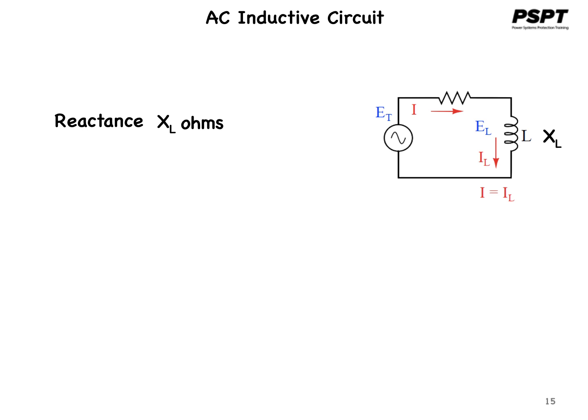Since inductors drop voltage in proportion to the rate of current change, they will drop more voltage for faster changing currents and less voltage for slower changing currents. What this means is that the magnitude of the reactance in ohms for any inductor is directly proportional to the frequency of the alternating current. Also, the magnitude of the reactance is directly proportional to the inductance of the inductor.